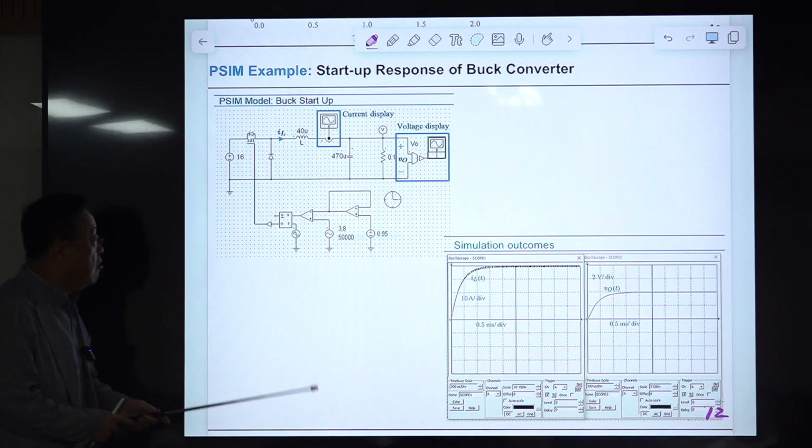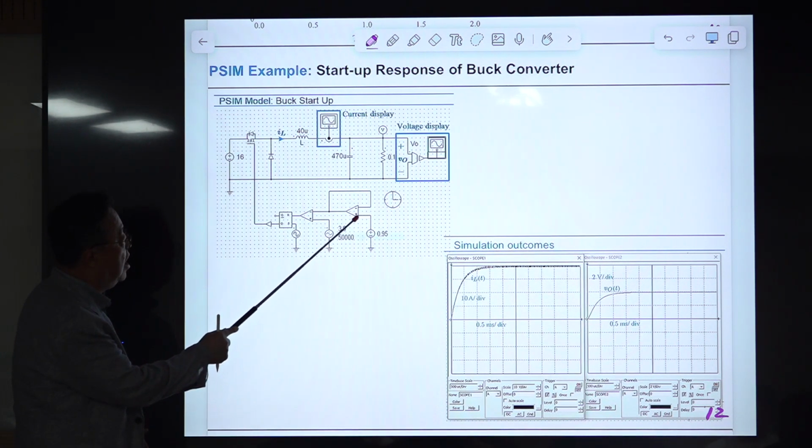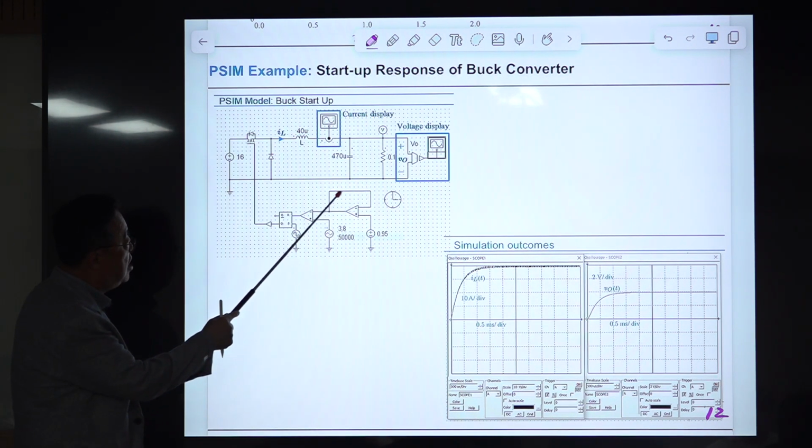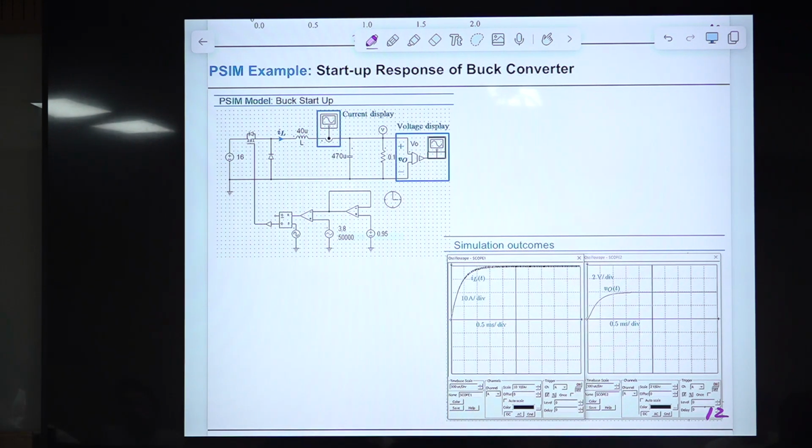Okay. So, and this is what? If you connect this voltage and these two ports are virtually connected, then that input voltage is the same as this output voltage. This is a unit gain buffer. So this is the unit buffer. Voltage buffer, actually.